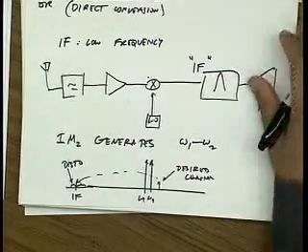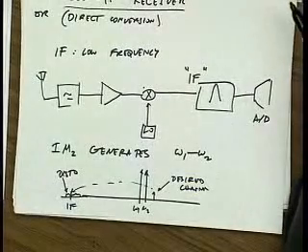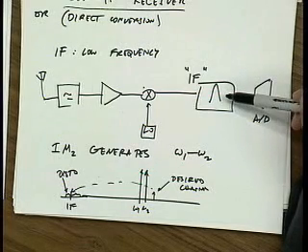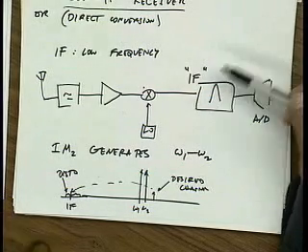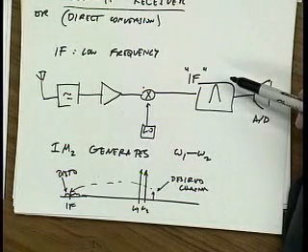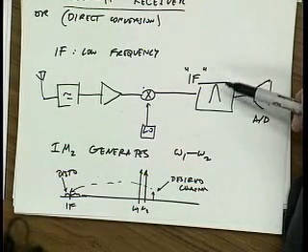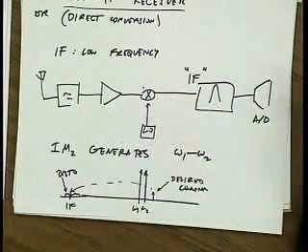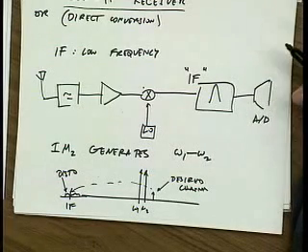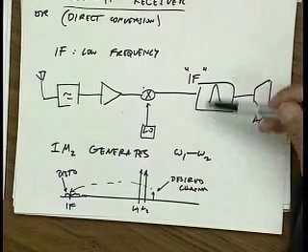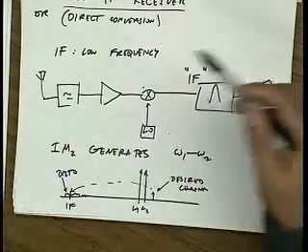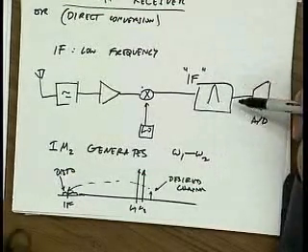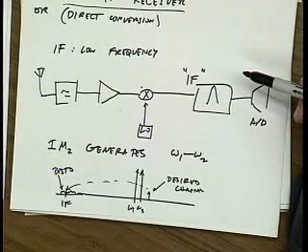It used to be that people didn't worry too much about IM2 in communication systems because communication systems used a relatively high IF frequency. And so you basically could AC couple and get rid of the DC offset and that wouldn't be an issue. Nowadays, it turns out that these kinds of architectures with low IF are much simpler to integrate. So either direct conversion or low IF, and they require minimal filtering. So for these systems, which are increasingly popular today, especially for things like CDMA, wideband CDMA, this IM2 problem is a very serious problem. Okay.